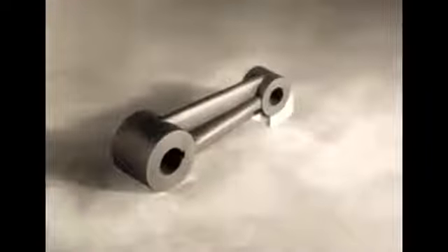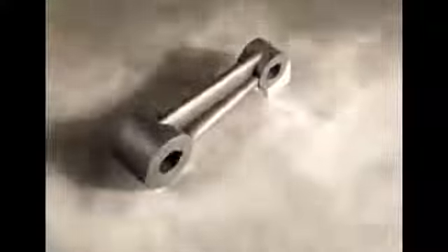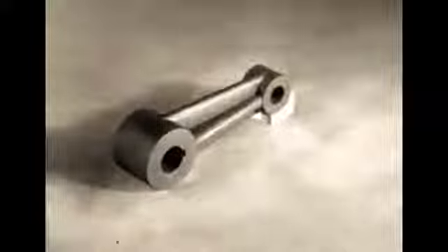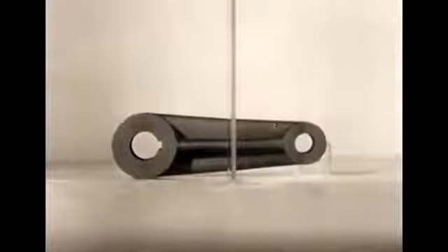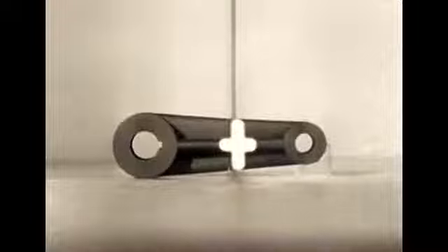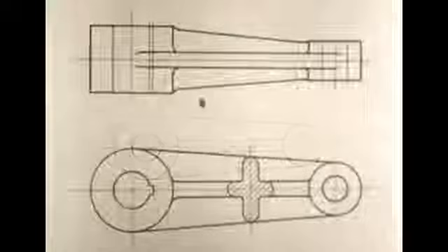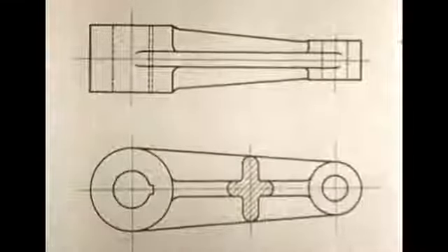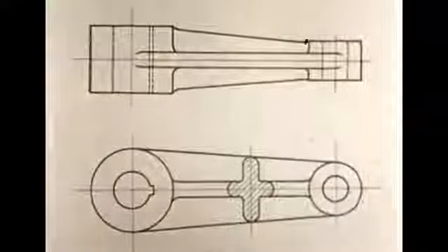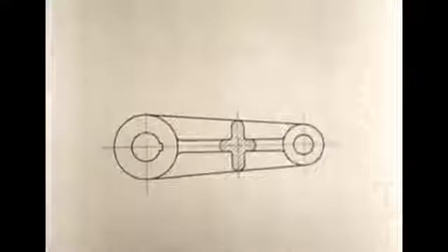Now and then you need a section only to show the shape of some detail, like a rib or the arm of a wheel. Think of a cutting plane that is perpendicular to the axis of the part you want to section. And think of the cut part as revolving or turning into the plane of the view. Then project the view and the part you have revolved, but omit the cutting plane line. When a section like this is shown right on the view, it is called a revolved section.